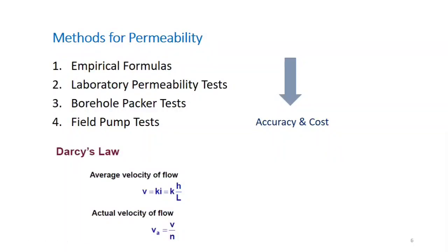Yeah, some basic review of the concept of permeability. You know, if you can recall Darcy's law, the famous law for flow of water through soils, remember its limitations. One of the limitations is that it's applicable to one-dimensional flow. So I would request again to go through the basic limitations and applications of Darcy's law. But never mind, what it gives you is the average velocity of flow through soil with this expression: velocity is K times i. K is the coefficient of permeability, or hydraulic conductivity, and i is the hydraulic gradient, which gives the head loss over a given flow path or flow length.